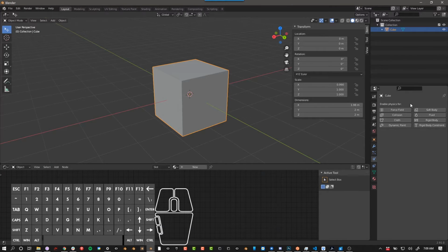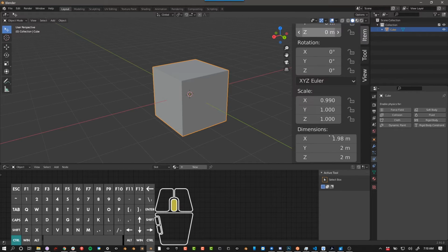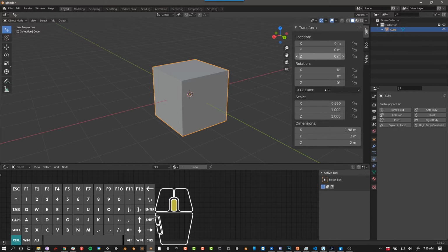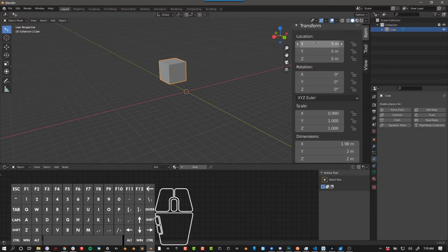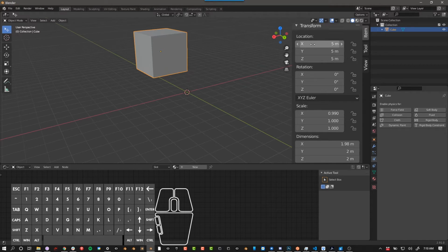Another thing that's interesting about Blender's interface is if you have a panel like this, you can hold Control and middle mouse to zoom it in or out, to make it bigger or smaller. As far as I know, that's the only way you can make it bigger or smaller. You have numbers like this. You can click and drag down to select all three of these, and then push 5, and it'll scale them all, or move them all 5 meters. Same thing, you could hover over those and push Backspace, Enter, and then it'll go back to the defaults.